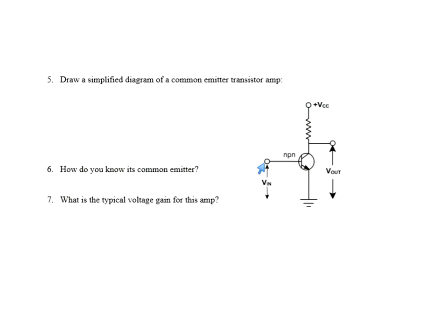My signal input comes into the base. My signal output is coming off of the collector. V in is on the base, V out is on the collector. The terminal that is not being used for input or output is said to be at common. In this circuit, it's very easy to see the emitter is at common. That's why it's called common emitter.